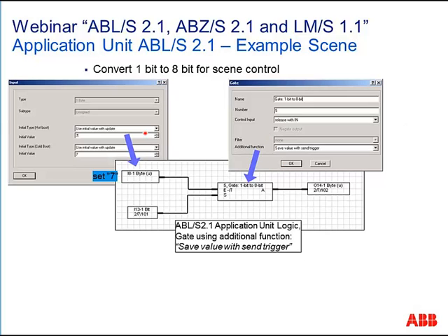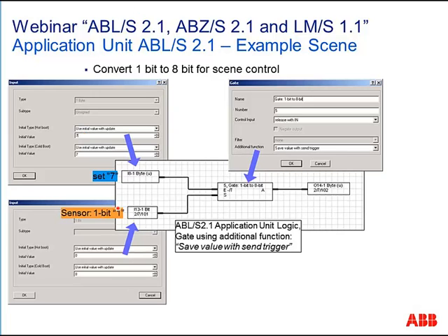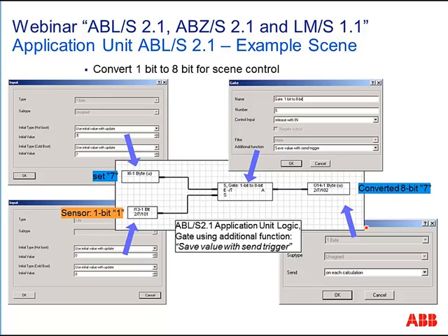So our input we use here must also be a 1 byte size. We specify here our initial value, which is 7, which means our KNX scene number 8. And on our control input, here we have the information, rain, which is 1. And we have here additionally on our output, also a group address as a 1 byte.